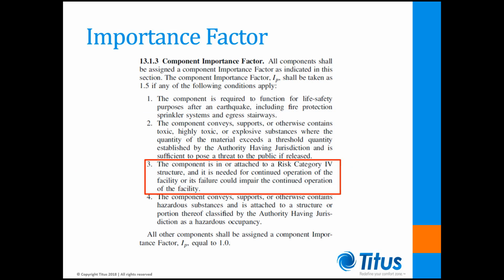Next, we must assign an importance factor for these terminal units. Looking at 13.1.3, the importance factor would be 1.5 since they would fall under condition 3.